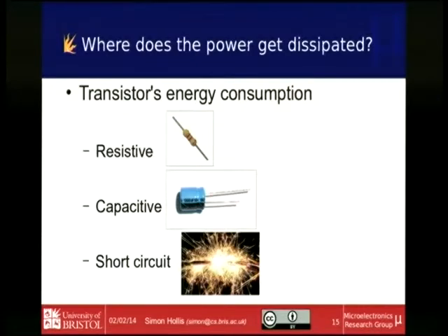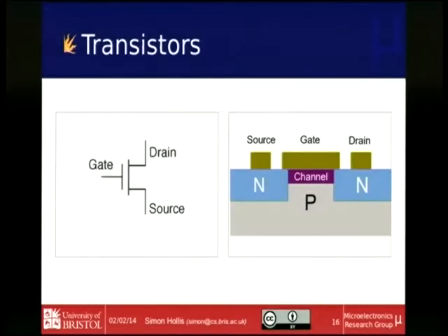But now we remember resistors and capacitors, and say these are the things that fundamentally take the energy of computation. So I'm going to talk about an area called dynamic power dissipation here, which is the thing that isn't just I've got a slab of silicon and I'm warming it up by just having a voltage across it. That's another part of the energy consumption of a circuit. But this is what happens when we do computation. We use these elements and they dissipate.